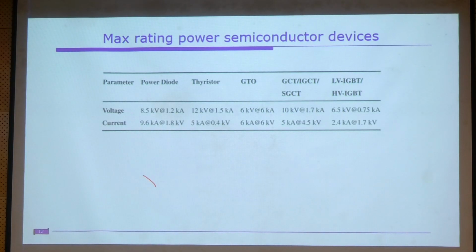But the drawback is that multi-level inverters increase the cost significantly. The main reason why we went for multi-level inverters from the industry point of view is the non-availability of the switching devices. All right. These are silicon-based devices, and manufacturers like Infineon, Wolfspeed, or ST Microelectronics keep two things in focus. The first is the current rating, and the other is the voltage rating.